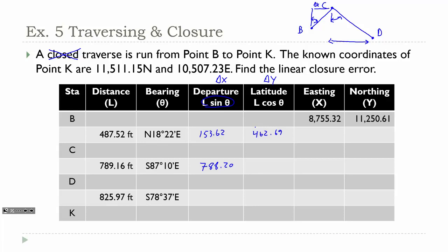So if you use the azimuth, it will give you the negative, but if you use the actual value, you have to, negative 39.01. Hopefully if you're using pen, you didn't scratch it out before you found out what the answer is. If you use the azimuth, it will give you the right sign. If you use the bearing instead, you're going to have to draw it out and figure out what the sign is.